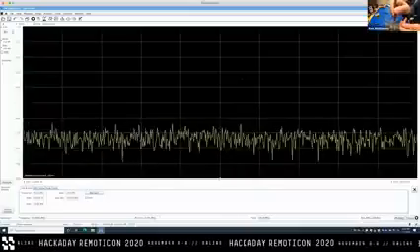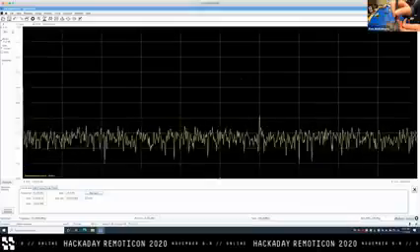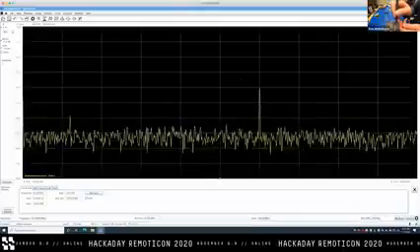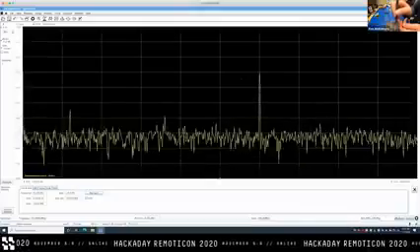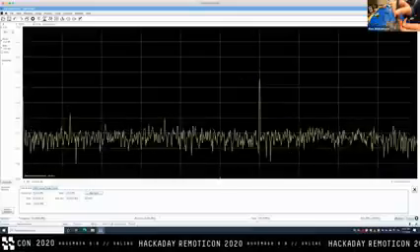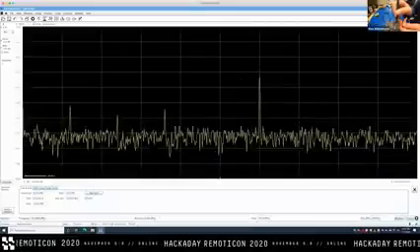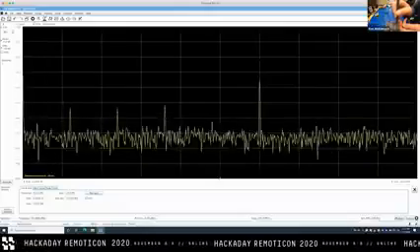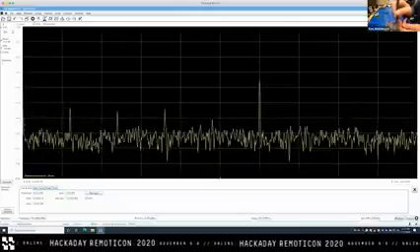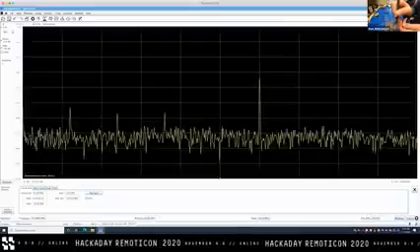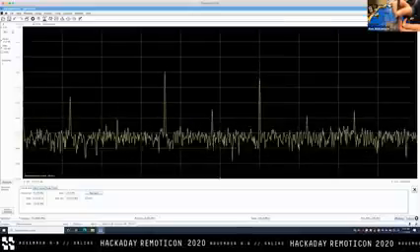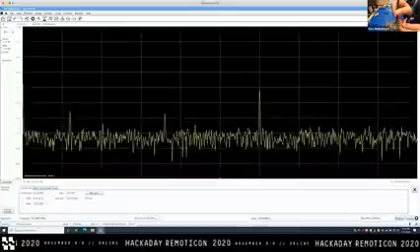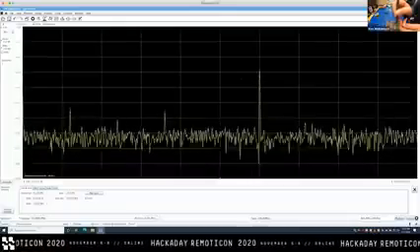If we move the probe orthogonal to the trace, so we're basically putting half of a current transformer next to the individual trace we're trying to measure, we can basically, with this probe, pick out nearly which pin specifically is actually emitting all this noise. And interestingly, we can see some new and interesting noise on other individual pins. But that's what's going on over here.